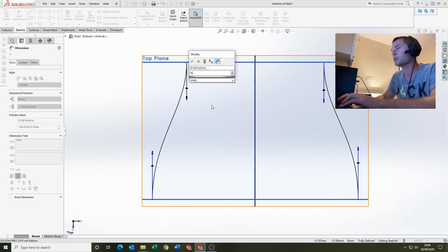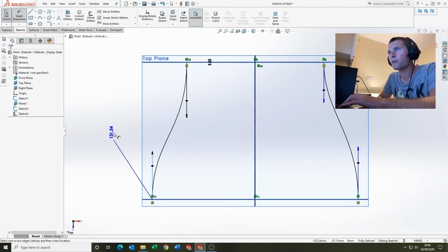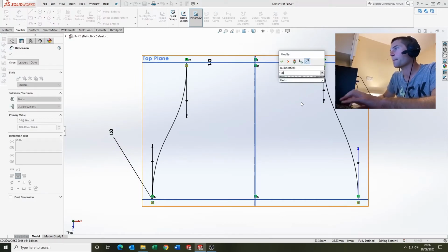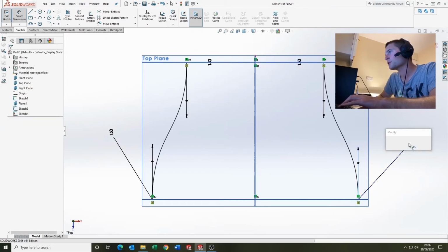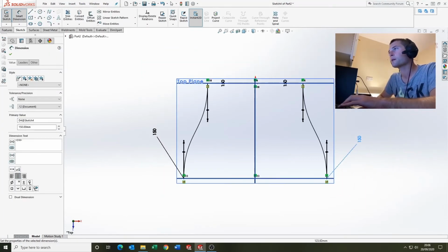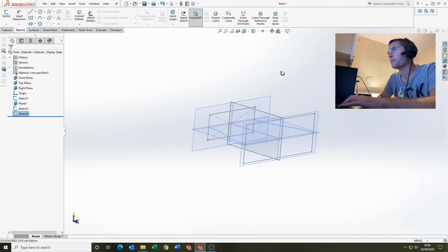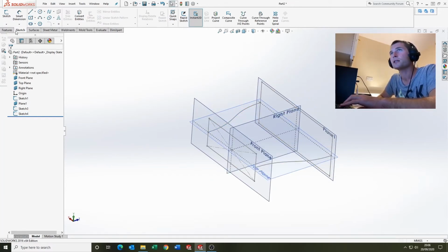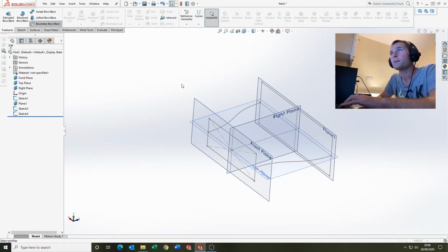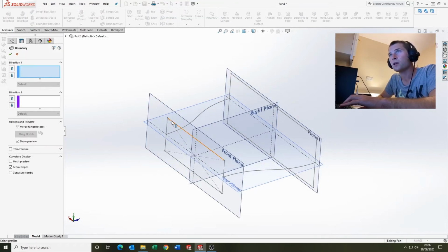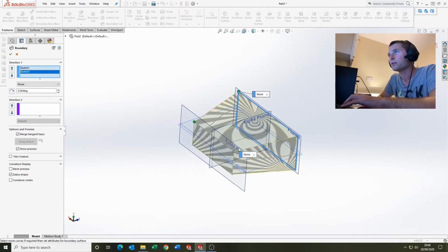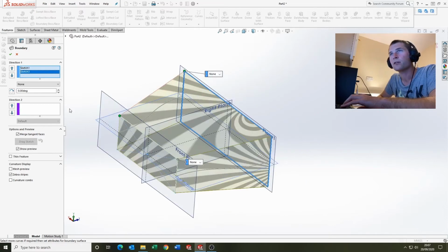do the definition. It's like the power of the spline to fully define them, and we're going to make them all the same, which is 150. And there we go. So now we have the fundamental building blocks for our boundary boss base feature. So direction 1, if you treat this like a loft, so we're saying that that rectangle profile is going to loft to the other rectangular profile.